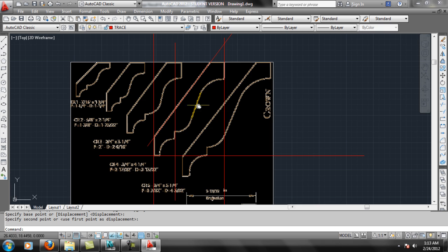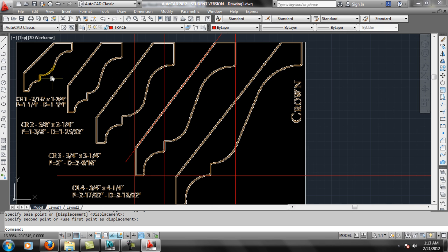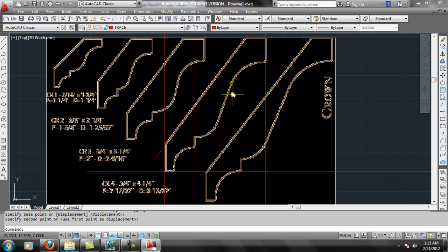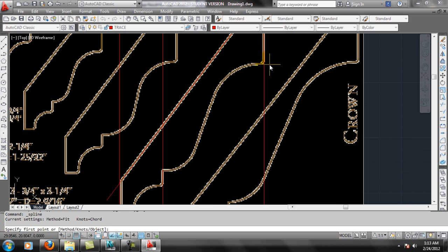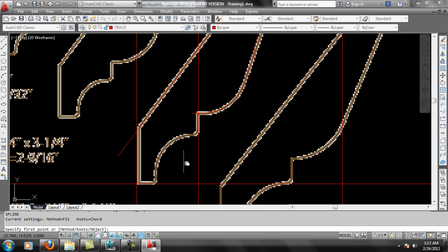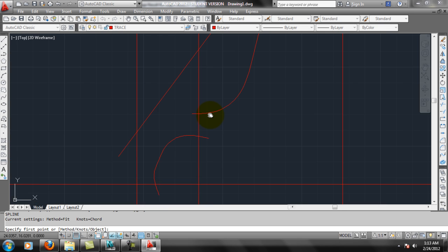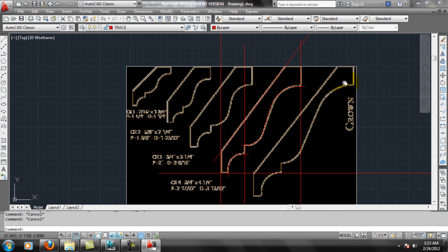But I like to use AutoCAD to trace this kind of stuff, again, because it's easier in many areas. So technically, you should draw individual arcs here. We'll go ahead and just use a spline tool because it's a lot faster. And you just click basically every so often. Overhang that and hit enter until it clears out. And I'll do that again down here. Alright, and basically now let's just trim this up.